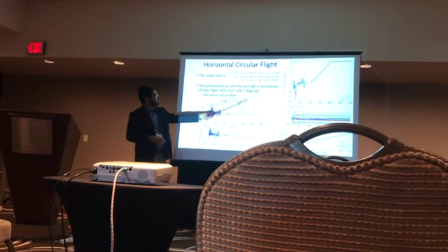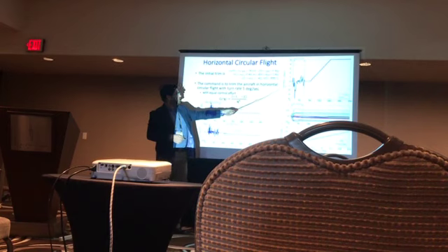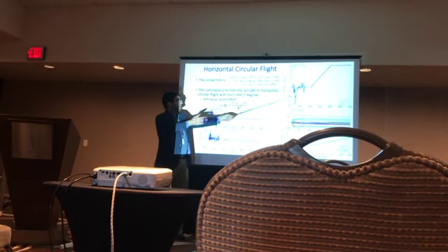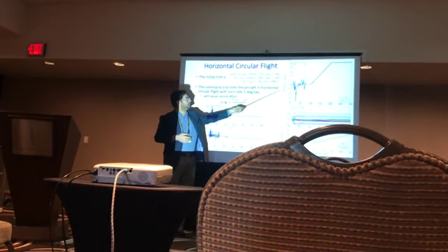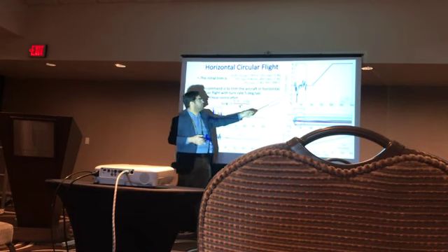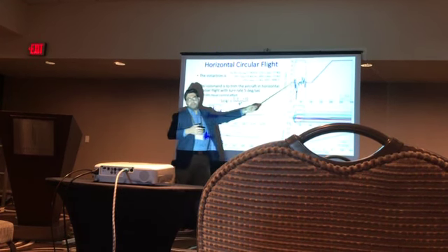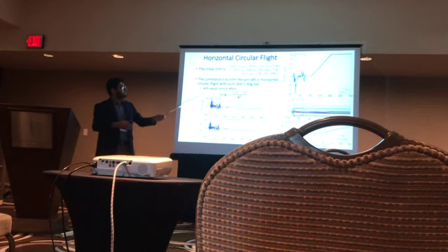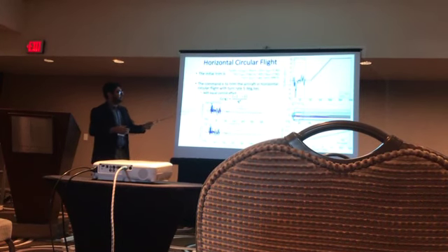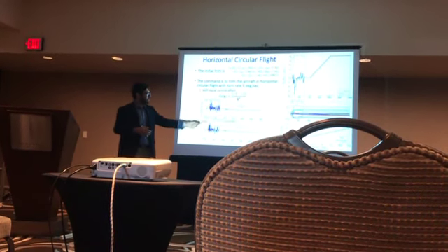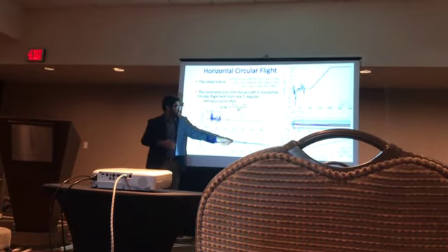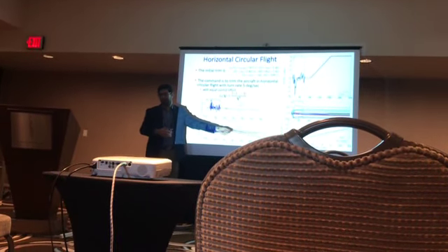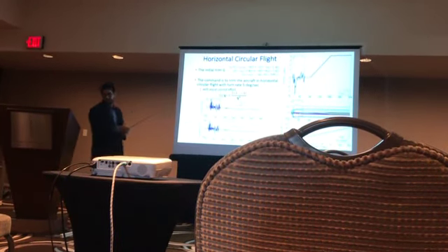And this one shows the turn rate. So initially we are going in a straight line, so there is no turn, and after a slight transient, the turn rate starts increasing and then converges to the requested value of 5. The controller coefficients converge, and this plot shows the U1 and U2, which is the aileron and the rudder effect. They are in the ratio 1:1.